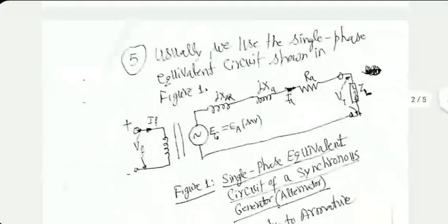Now, the analysis of three-phase AC generators is normally done on a single phase basis, because you know the other phases are out by 120 degrees or 240 degrees. So if you can model one phase accurately and assuming a balanced system, you can predict the performance of other phases with a reasonable amount of accuracy. So typically, we draw the equivalent circuit of a three-phase generator based on a single phase situation. And this is how we draw it. It is based on common sense.